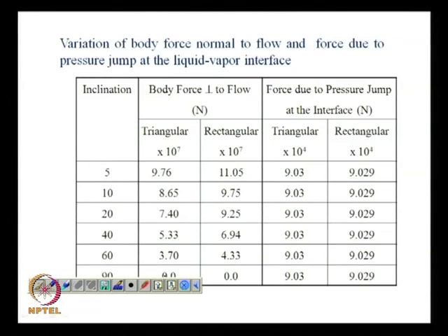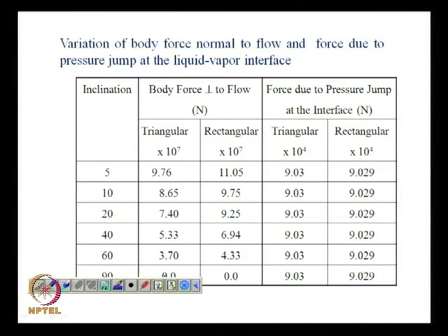We keep on saying in microscale devices that body forces are rather unimportant. It is the surface forces which govern the flow, and that fact is verified here by looking at the values of body force and the values of the force due to pressure jump at the interface, which can be evaluated by the Young's equation, and there is an orders of magnitude difference between the two.